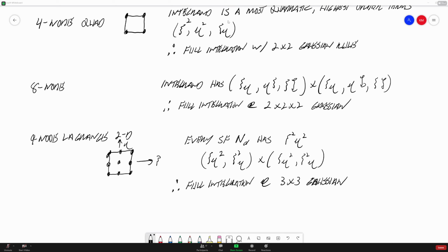And then you go through and do this from a finite element perspective and try to quantify the effects of some of the different assumptions in the mathematical routine, to show where the actual error is. Identify: is it on the conservative side, meaning does it lend a larger displacement, or is it non-conservative and give you a smaller displacement? And does everyone know what I mean when I say conservative with regards to the displacement?